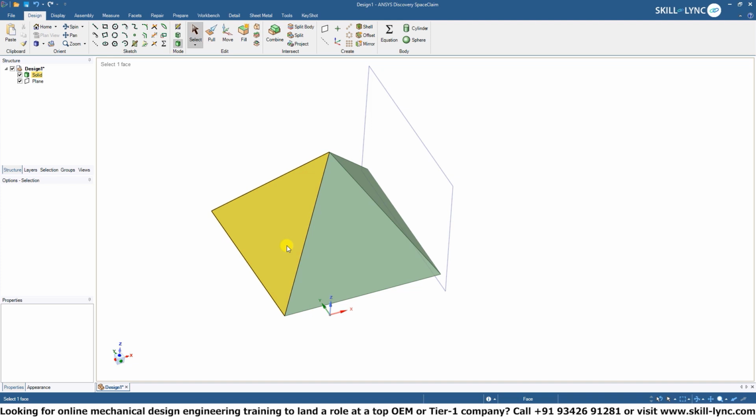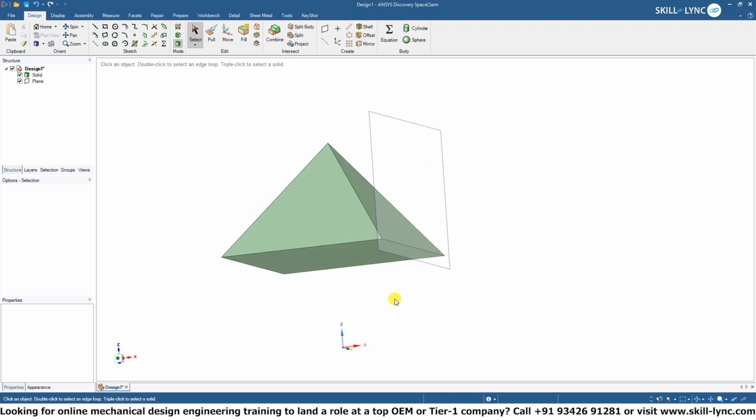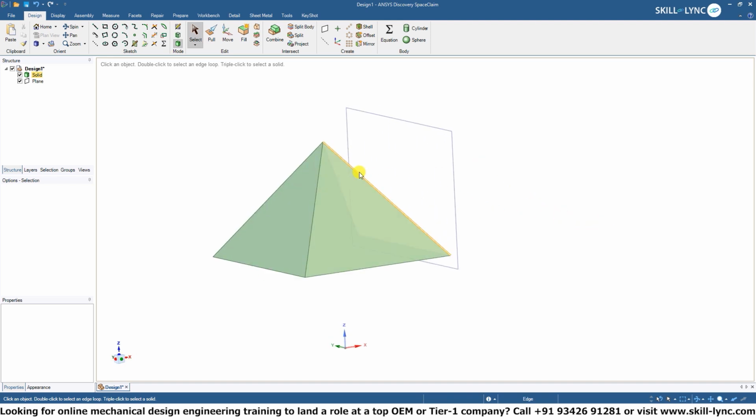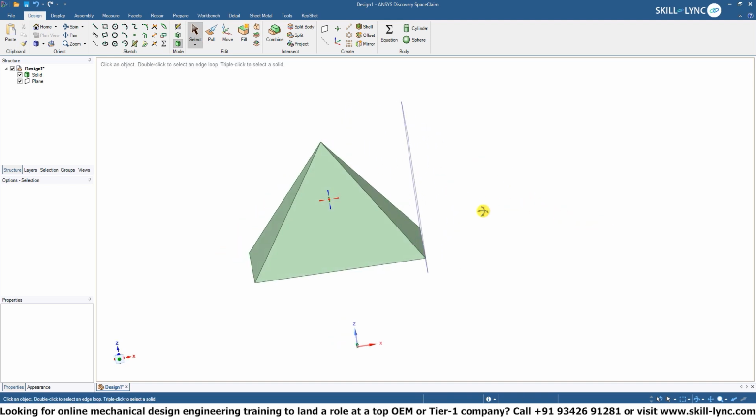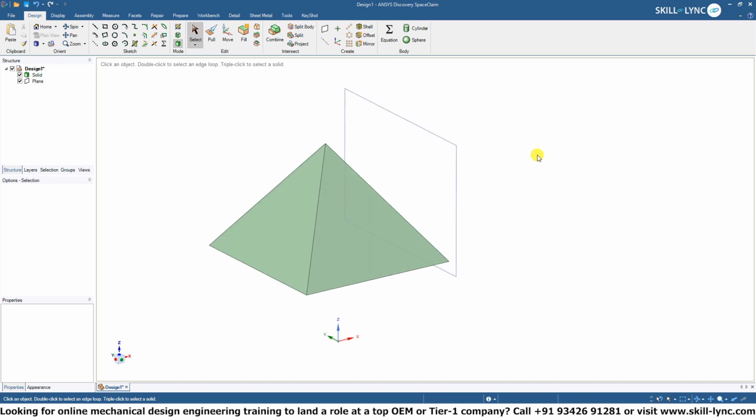After a bit of brainstorming and playing around with the model, I said, maybe it's because I'm working off of an angled sketch plane. So, using that hypothesis, I created another sketch plane that was purely vertical to see if that affected my model in a different way. As you can see, that yielded a better technique to cut it.